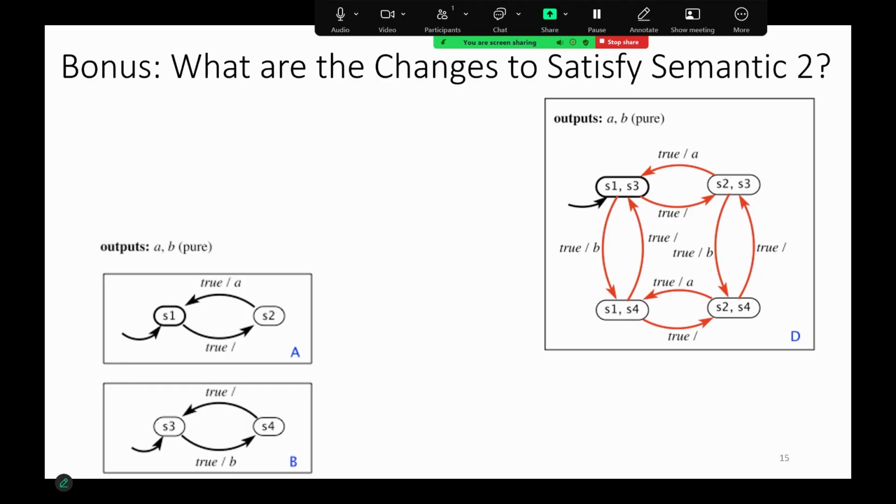If you are at S1 S3 and you would like to change both at the same time, you will add a transition to S2 S4 as you mentioned. So upon this you are getting true, so A and B will react simultaneously and you'll have a transition like this.